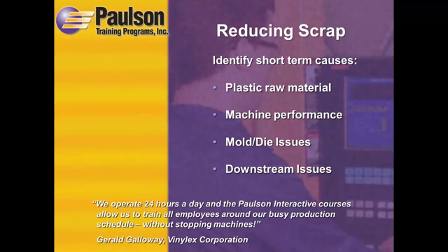Second one that happens a lot is machine performance. This includes things like maintenance, whether the machine's calibrated properly, whether it's operating to spec. And I'll be honest, all the time I've spent in plants, new machine versus maybe a little older machine, doesn't matter all that much. I've seen plants where older machines are properly calibrated and tuned up and well-maintained that embarrass plants with newer machines that aren't as maintained, never been calibrated properly, or more commonly than all, nobody knows how to use them properly and their full capabilities.